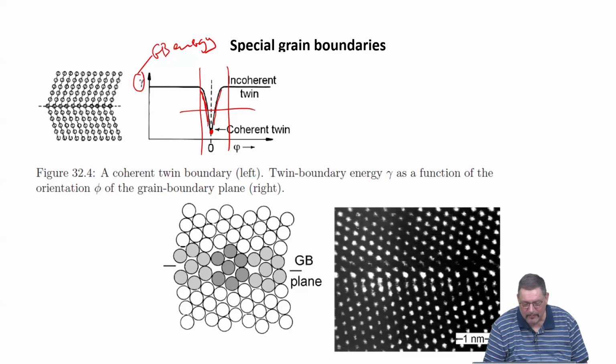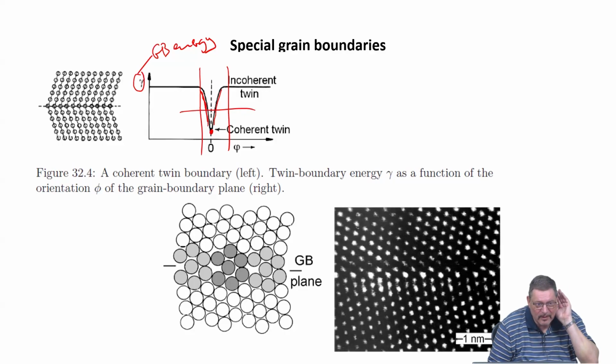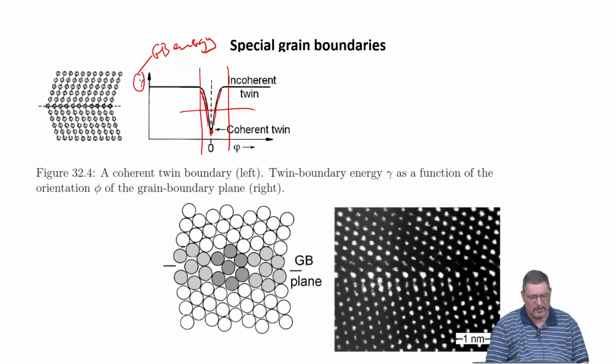Yeah, and if you anneal them, they tend to be getting more coherent, because annealing would serve to allow the material to find lower excess energy states, and this means it likes to form the twins, the coherent twins, if there are already twinned structures available. But it depends on the kinetics of the process, like how high is the temperature and how large are the activation barriers for the jump, specifically in this already twinned structure. So it depends very much on the material, how long you would need to wait.